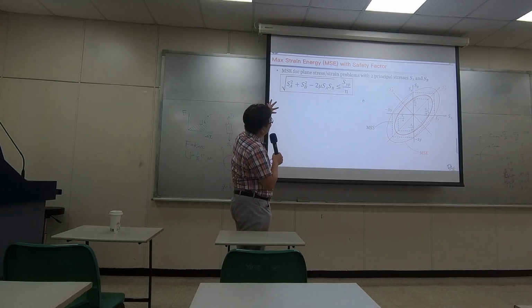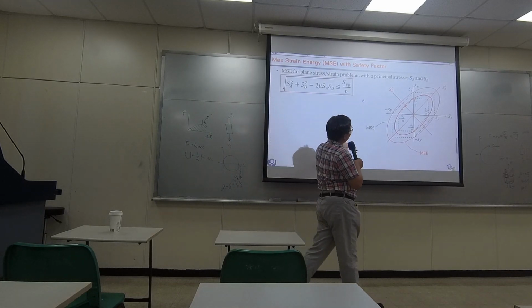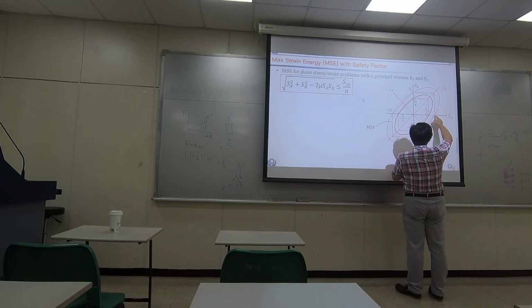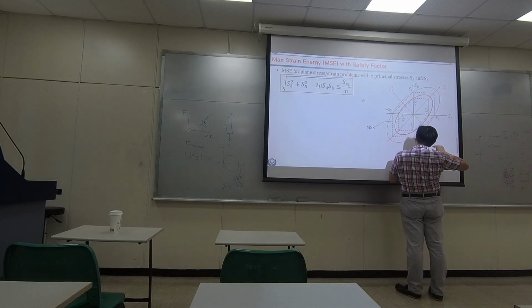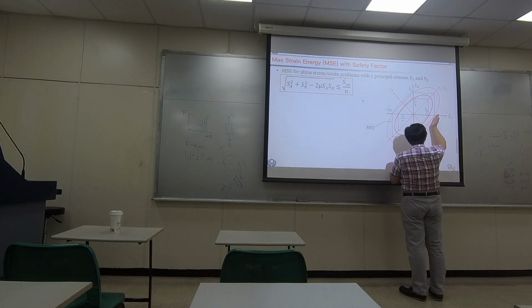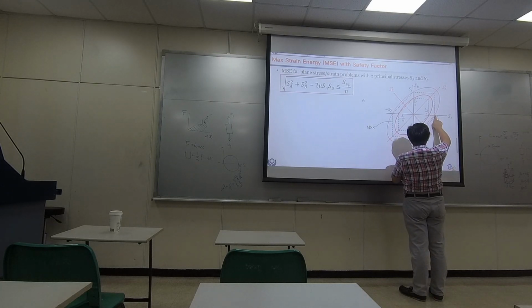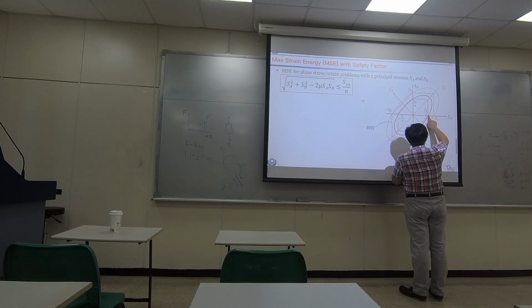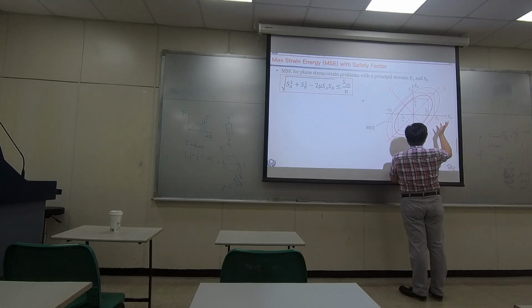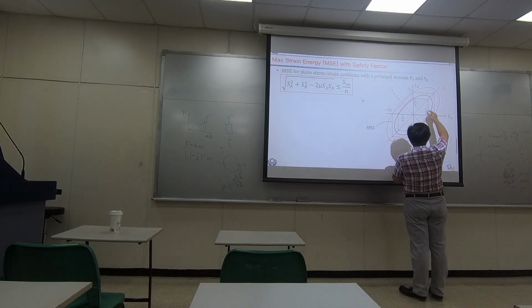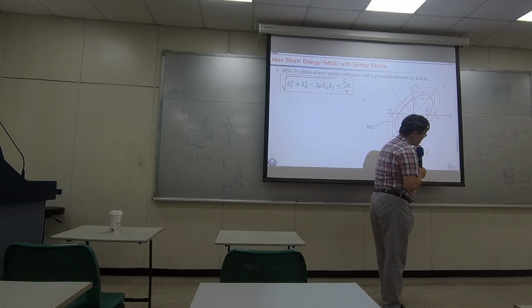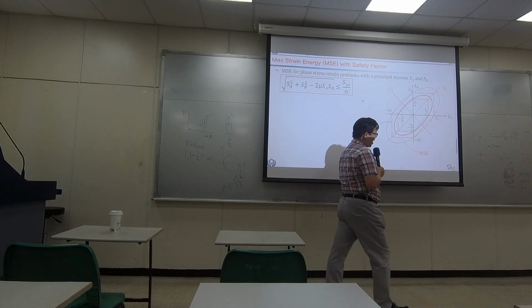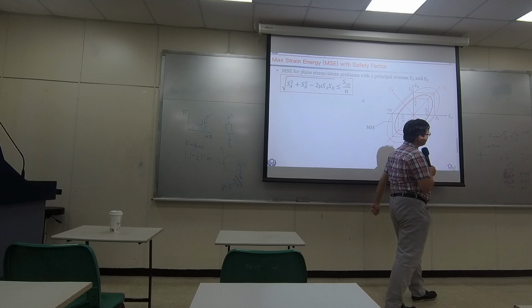So, when we do that, it's just like you are pushing this elliptical limit from the yielding point to somewhere inside. How much further inside? Basically, divide Sy by a positive value n, also greater than 1.